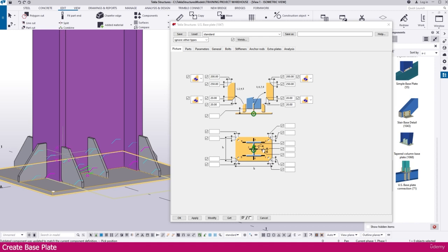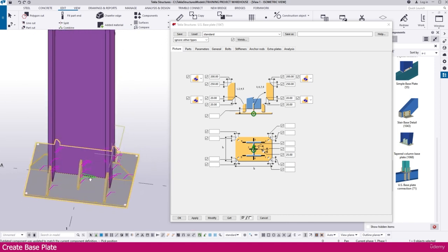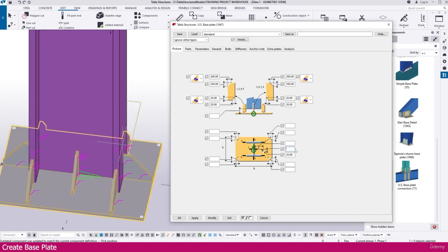Now if you need a grout hole, if you require, you can make the grout hole also. Definitely a grout hole is required. I just make it 25 dia or 50 dia, depends on your project requirement. You can make that one. Then here it is coming somewhat center. I just make this one a little bit, make it 50.